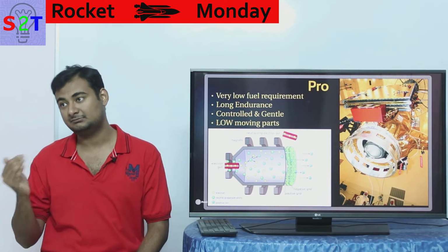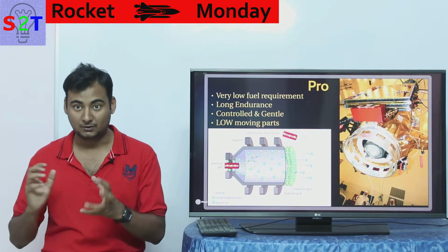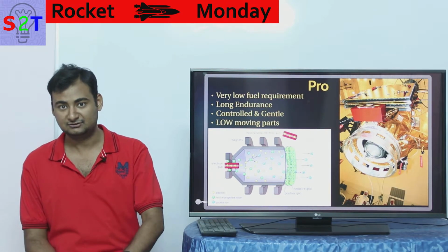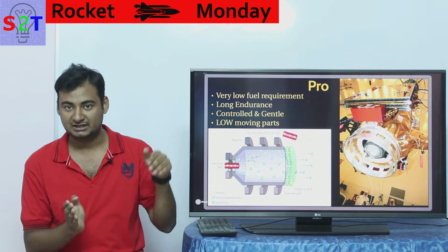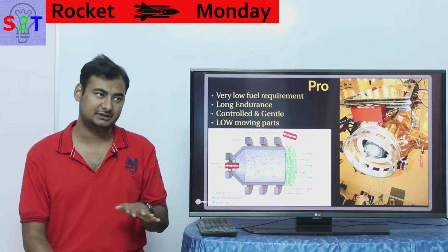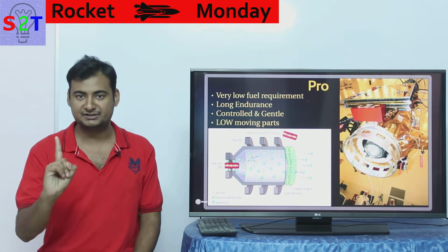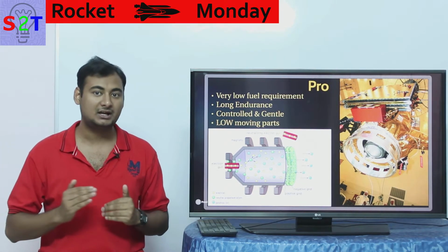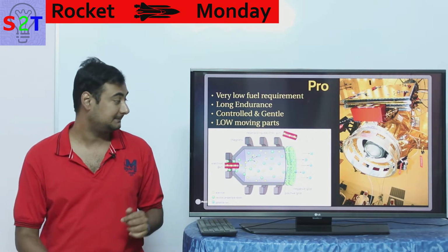You can do that. Many of you who have been following SpaceX know they say throttling a rocket engine is very difficult. It's very tough. You cannot go from 0% throttle to 100% throttle reliably. Generally you have an operational range where 100 to 70% is the throttle. They can go down some, but they cannot go very low. But in these puppies, you can go 1% throttle, 15% throttle, 100% throttle. This whole aspect of controllability really allows you to do station keeping properly.